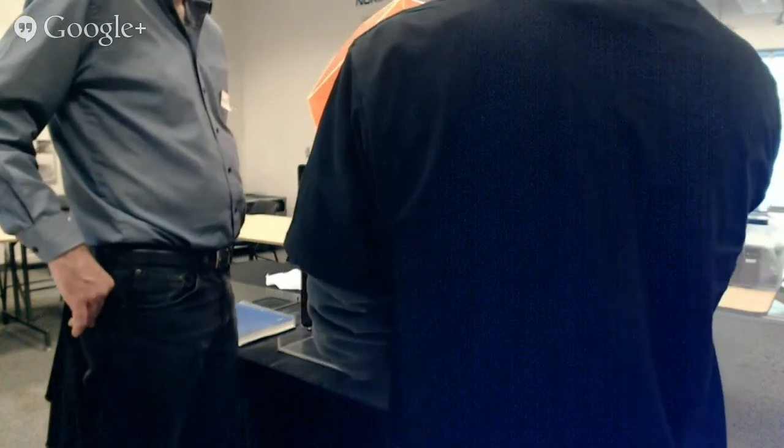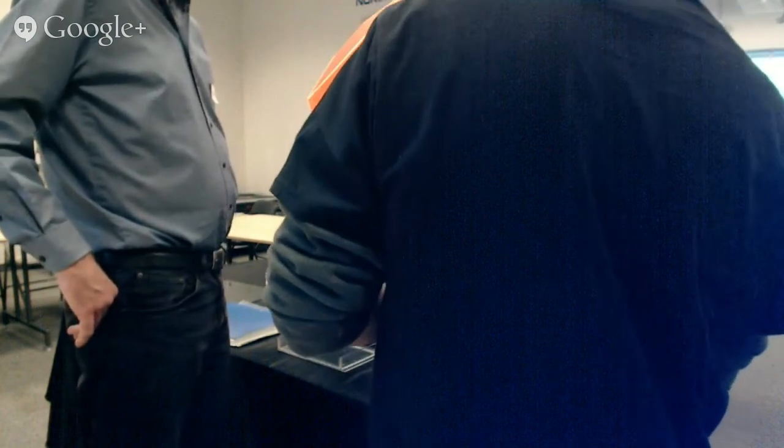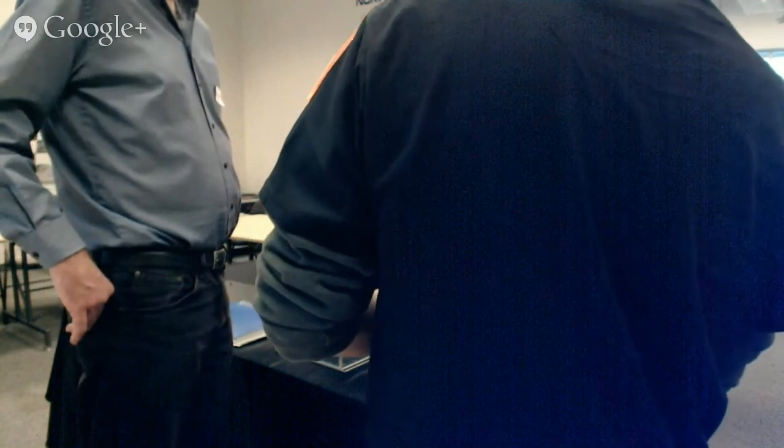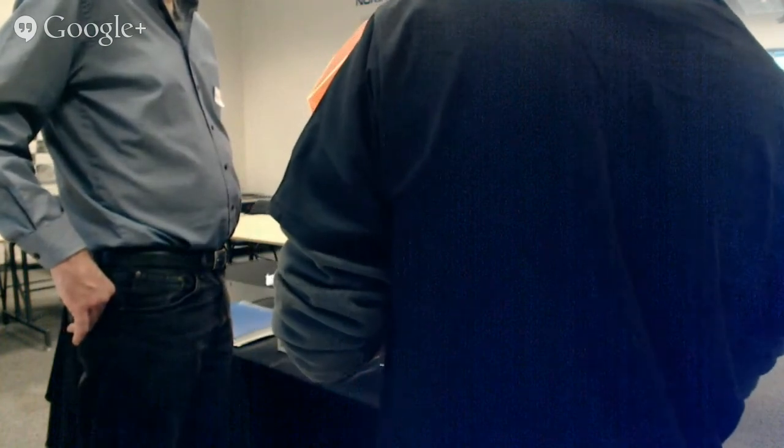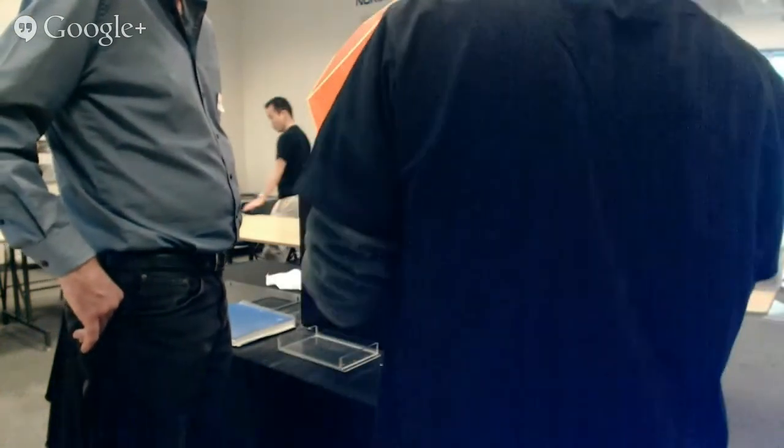I mean, there are a bunch of other tricks to get this part. This part kept pulling off the build plate. And so in order to keep it from pulling off, I have supports that stick out laterally outside, in parts where the surface finish doesn't matter. If I needed surface finish on every single surface, I wouldn't be able to do this. But I said, this part here, the surface finish doesn't matter. The mold is only going to go like this. Sides don't make any difference.